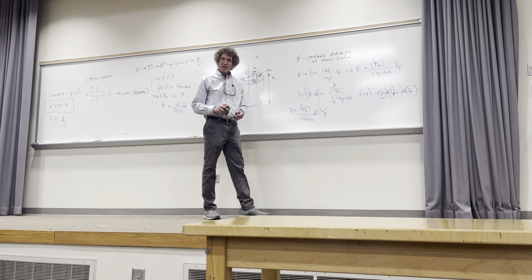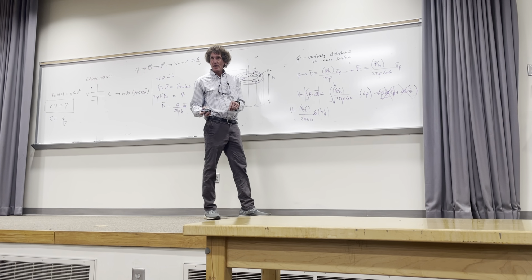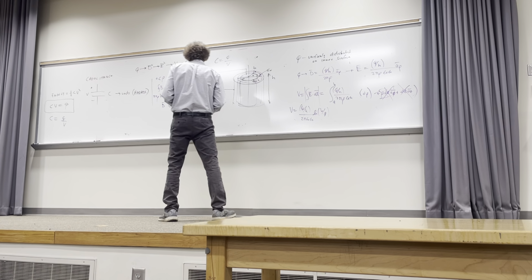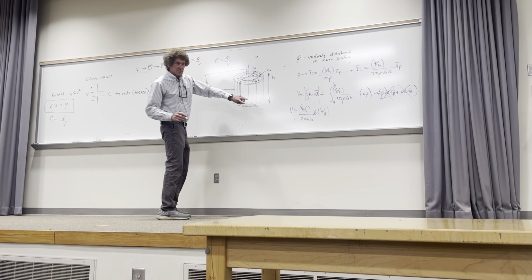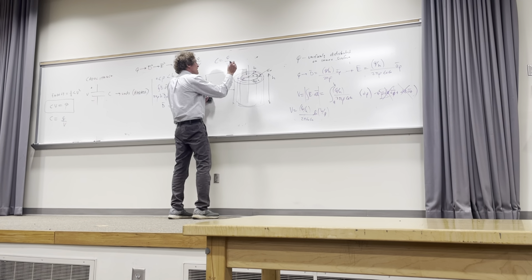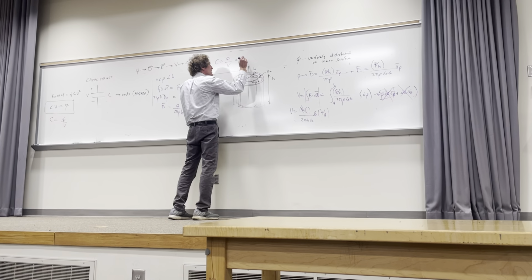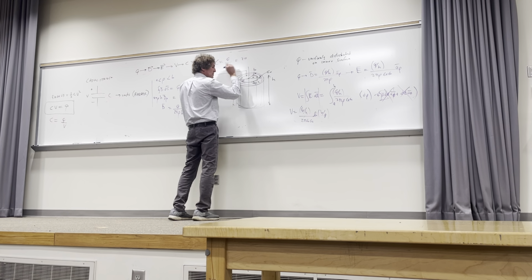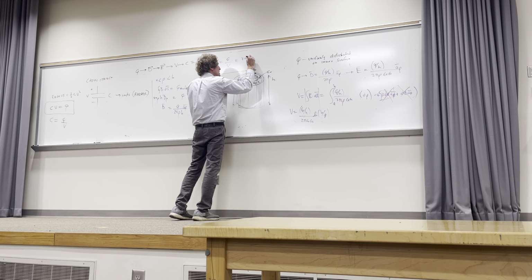You all follow me? It's B over A. After you integrate it and get log of rho, you have to evaluate between the upper and lower limit. You all follow me, guys? All right, and that means the capacitance here is Q over V, or really just flip that whole thing. And you get this equal to 2 pi epsilon relative, epsilon naught, and then it's divided by the natural log of B over A.